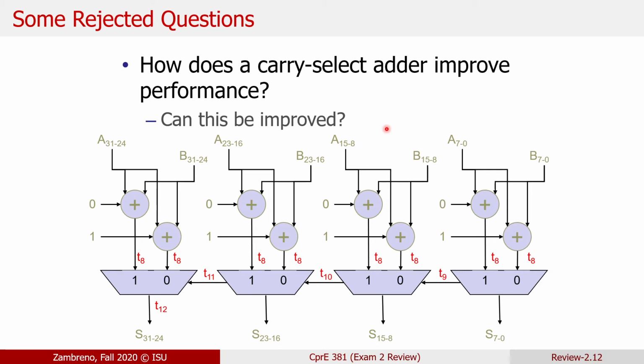So there's a lot of different ways one can implement an adder. And in fact, we didn't really even talk about the carry look ahead adder other than a little homework question that talked about it in some brevity. This is a carry select adder. So the question would be having something to do with understanding how the carry select adder works, and from this diagram, can you explain why this gets better performance than a typical ripple carry adder? I'll call this a rejected exam question because that's a little too difficult.